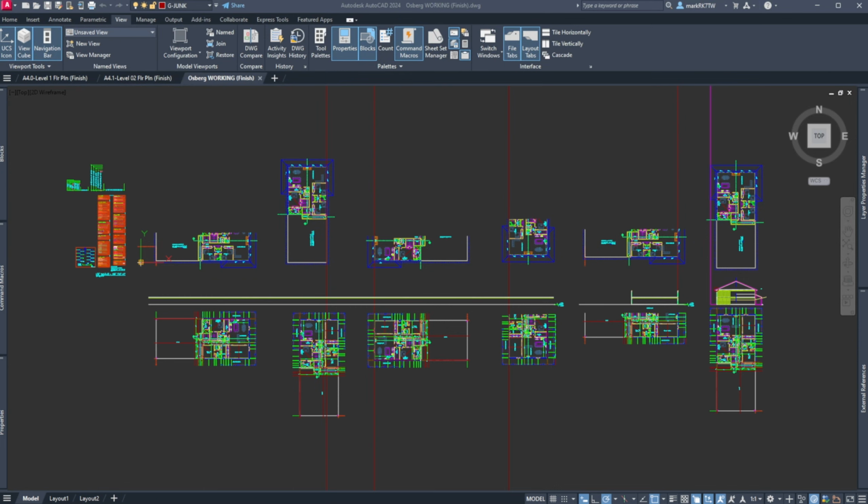There's one other thing that's pretty important. Well, there's a couple of things. There's headroom, which is the one that I really look at in section and make sure I got it right. The headroom in the stairway should not be less than 6'8" measured vertically from the sloped line adjoining the tread nosing or from the floor surface of the landing platform on that portion of the stairway. So we'll do this and we'll show it for you.